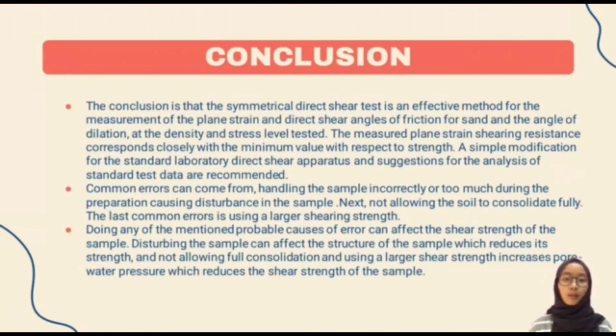Common errors can come from handling the sample incorrectly or too much during preparation, causing disturbance in the sample. Next, not allowing the soil to consolidate fully. The last common error is using a larger shearing strength.